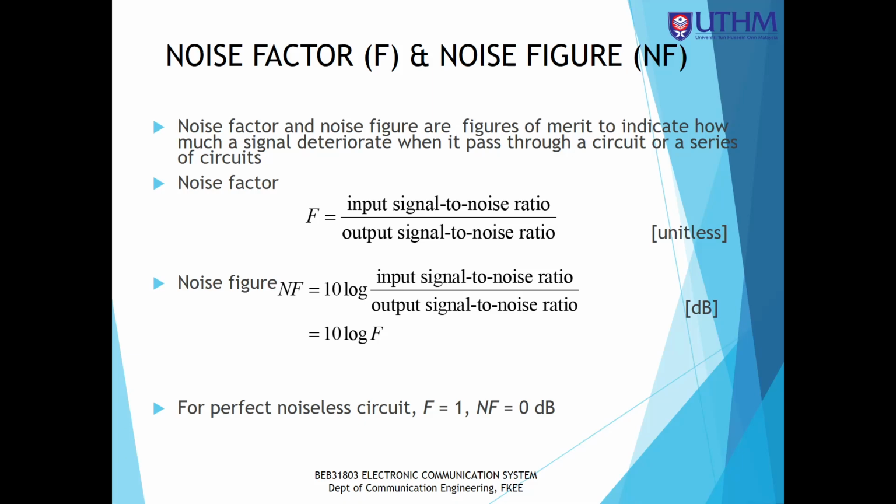So noise factor is equal to input SNR divide with output SNR. Okay, so SNR input divide with SNR output. Input over output, not output over input. Don't do careless mistakes. This is about SNR input over SNR output.